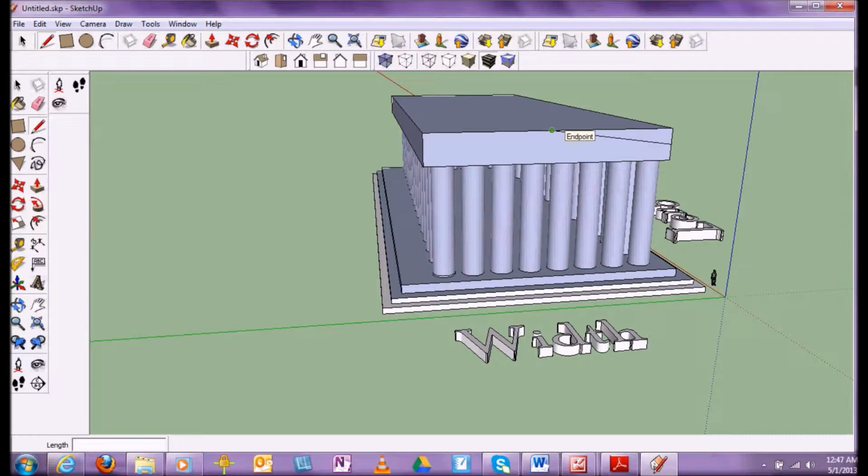It should say end point in this case, but it's going to be the midpoint because it's picking up on the very last end of our previous line that we drew, which is an end point, but it is also in this case the midpoint. So we will click and we'll draw a line to the other side till we see the word midpoint. That's the inference from SketchUp. It's going to tell you where you are, and in this case we're at the midpoint. We click.